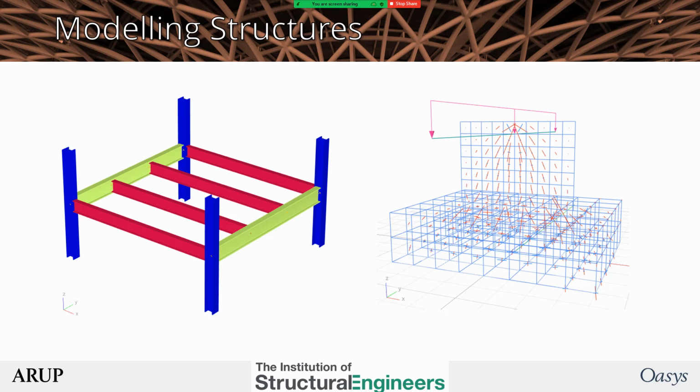Now, these are all analogies, and these analogies will break down when the stress flow directions change, like at the connections between the beam or slab and the column. And for this reason, a simple overall model can inform a more detailed model of a part of the structure, but you would not want to model the entire structure in such detail. You would not want to model either of these two examples totally in 3D elements. It would be a complete waste of time.